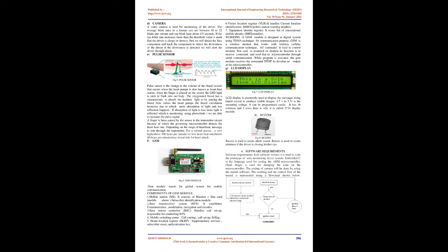B. Power supply. The power supply consists of several parts like AC supply, transformer, rectifier, filter, regulator, and DC output. The AC supply is 230V. The transformer converts the incoming voltage to the voltage required by the device. The rectifier rectifies the incoming AC voltage to DC voltage. The filter filters out the roughness of the DC wave. The regulator stabilizes the ripple voltage so that the components connected to the power supply do not get damaged. The power supply brings life to all the components. The power supply is given to the microcontroller using a screw terminal or through the USB port.